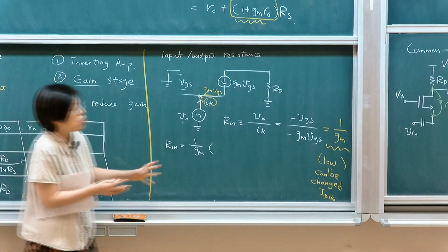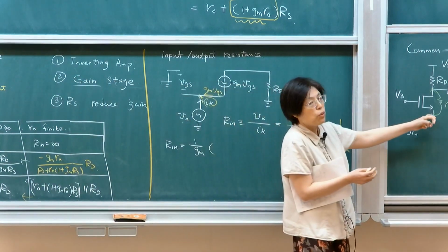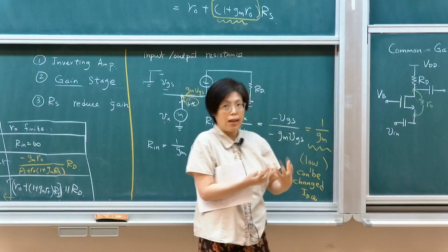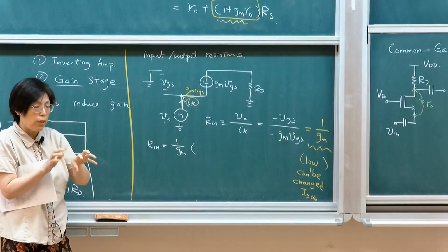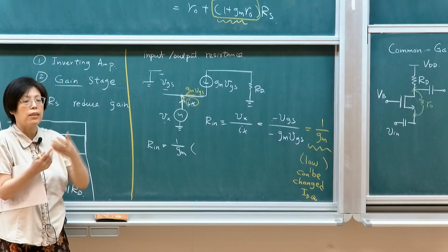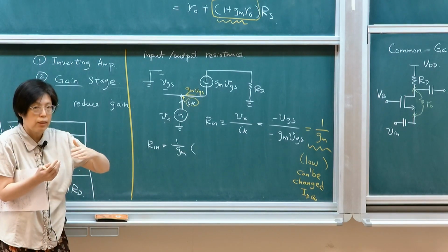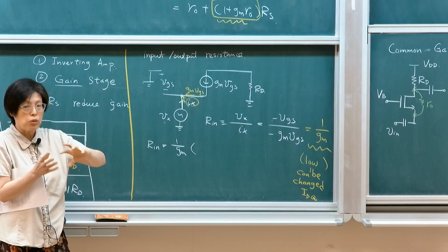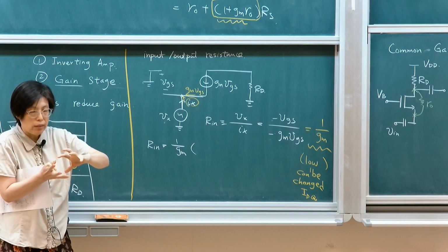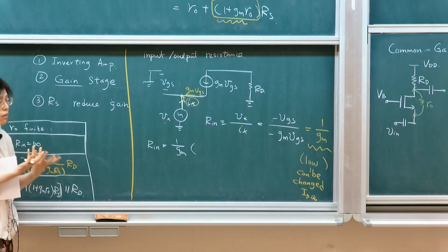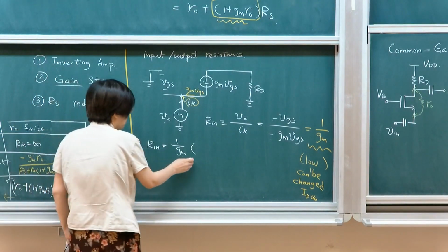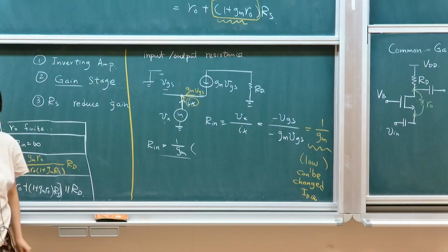Typically, the source terminal is the lowest resistance node, meaning that it has a large amount of current. Low resistance means that if I modulate the voltage, the current required to modulate it is fairly high. That's how you get low resistance, so it provides a high current node.